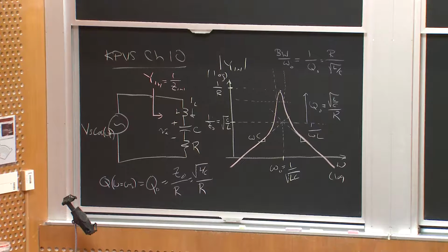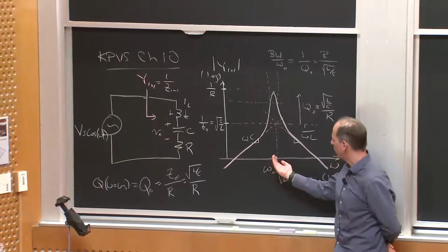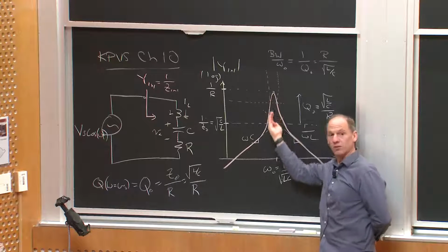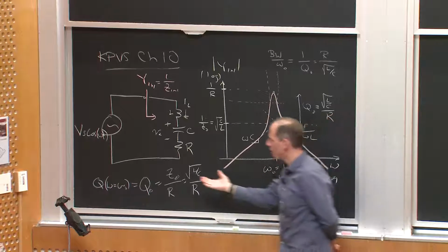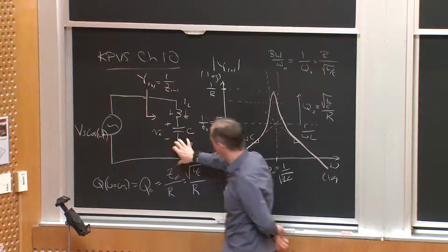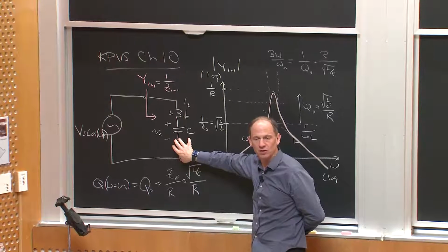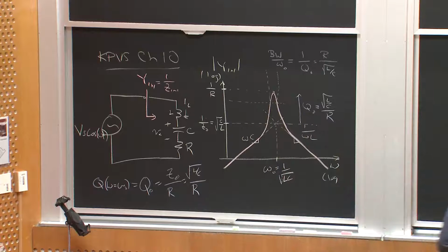How are we going to use this in a power converter? Especially if it's a high Q network, this high sensitivity to frequency means that by modulating the frequency of some drive waveform, I can very easily modulate the power going into the resistor, right? So using frequency modulation isn't always the way you operate a resonant converter, but it's a very common way to operate a resonant converter.